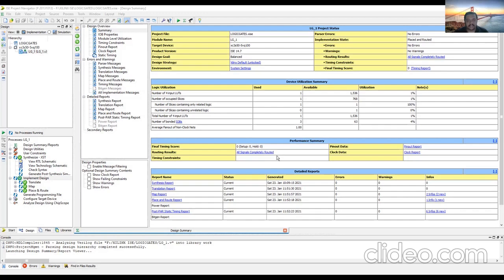The same web page will be appearing, but over here it is called modify license if you are going under the manage license tab. Here it is called generate node locked license. So it is coming ISE WebPACK license. Here it will ask for the system information, host ID, any, nothing, comments, nothing. Click on next.